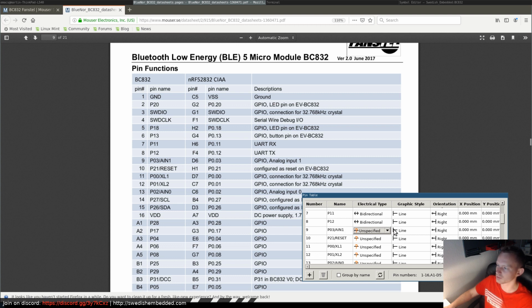But even the basic one can detect things like if you connect two pins that are outputs together, it will generate an error so that you can fix that fault, because you don't want to have two pins that drive each other. Although I do agree that, with bidirectional pins, actually I think it generates an error for bidirectional pins as well.